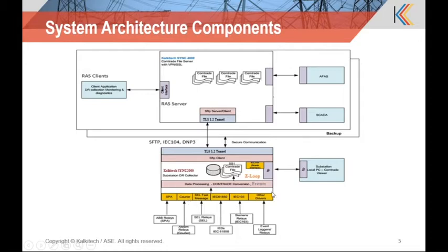As I have mentioned, this is Sync 2000. There can be multiple protocol drivers collecting the data from multiple relays, and we have all these drivers available, whether it is SPA, Courier, Schneider relay, SEL fast message protocol, 61850, 103, and other drivers like GE, custom Modbus and other protocol functionalities. And these collected disturbance files are in their own proprietary format.